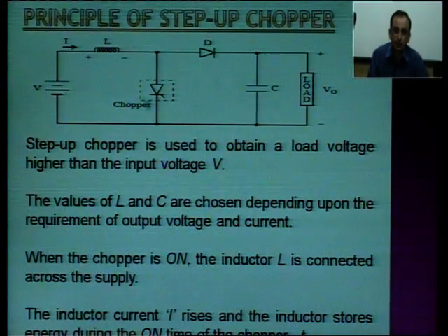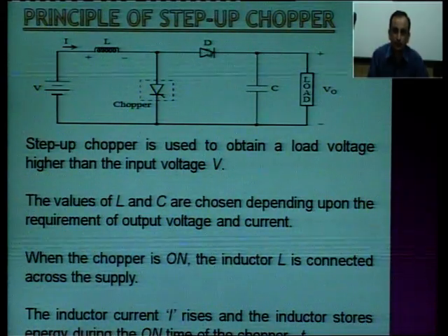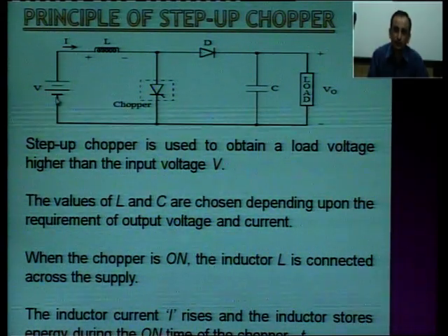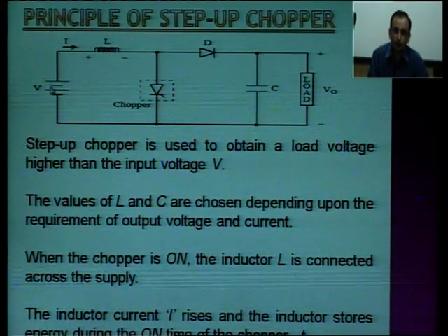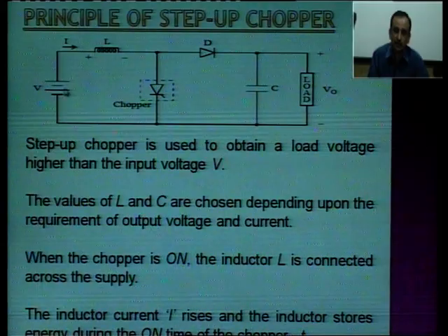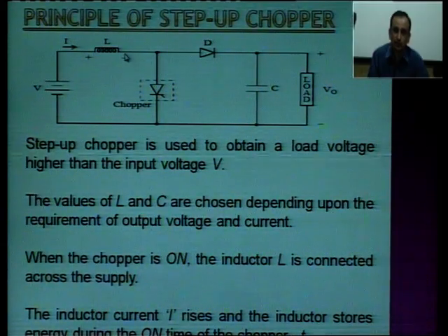Now, the chopper is connected in this way, we connect a load here, there is a diode, and we apply some voltage across this. Whenever we turn on this chopper, it is conducting, acting just like a short circuit. So, this V is directly applied across your L. It is storing energy during this time, this is the way the current will flow.